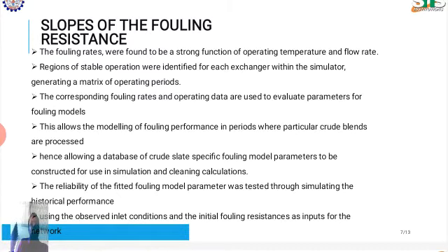The section AB is a region of constant throughput, where the furnace is able to accommodate the reduction in CIT at the target throughput as the furnace has not reached its duty limit. Section BC presents a region where there has been a reduction in throughput as a consequence of the furnace reaching its maximum duty with fouling.